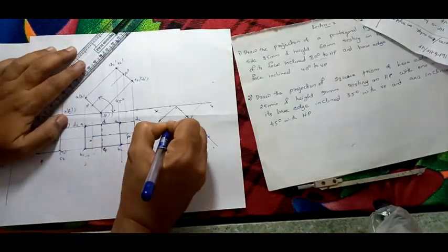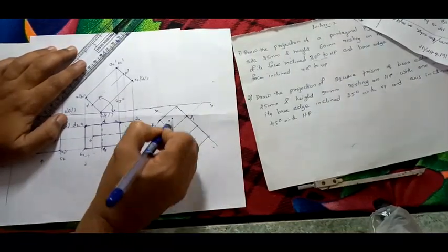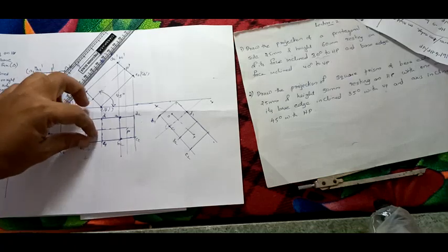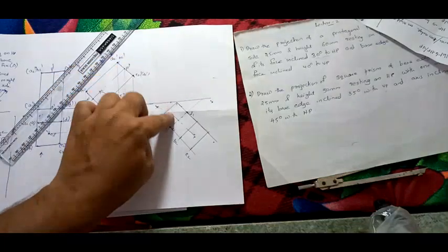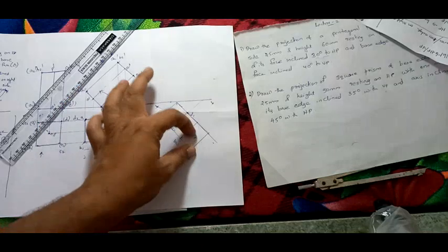Now find OP. I am not going to tell much about that. You have to find it. Simple, right? OP you have to find. How? If you want to find OP, take distance from O, cut an arc here. So take C1, cut an arc here. See, you can obtain OP. Then draw a line parallel to this line, in order to meet here. Why? To find P, take any C to P distance, cut it on the line.